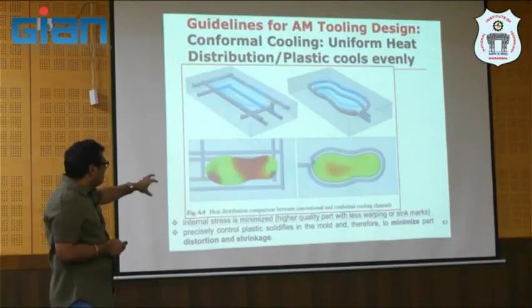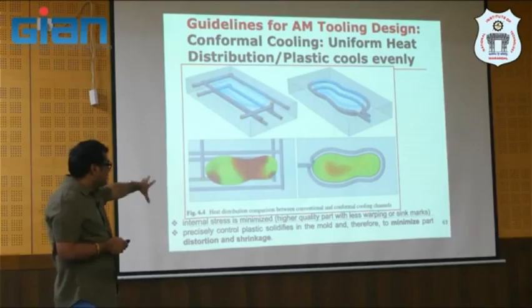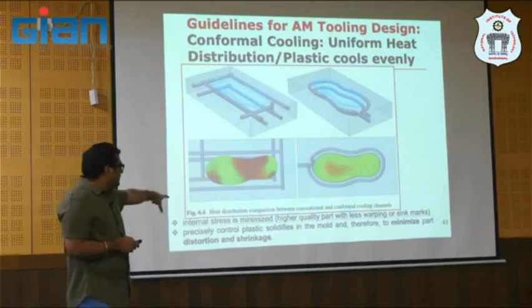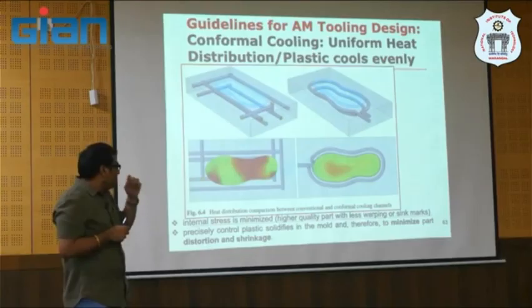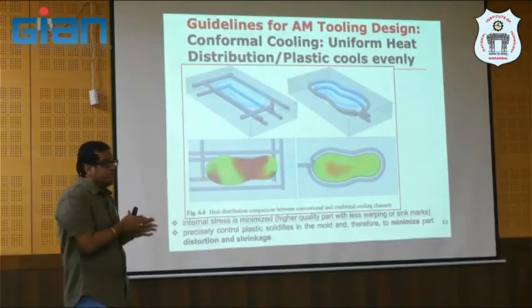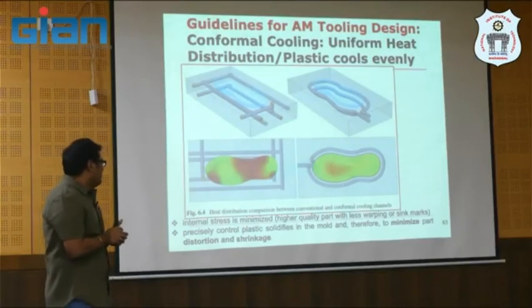If it is a traditional tool, you have a lot of internal stresses, which we can see on the left figure. And on the right side figure, if you see, the warpage or the shrinkage is minimal in the case of your conformal cooling channel, right? And your distortion and shrinkage are all minimal.